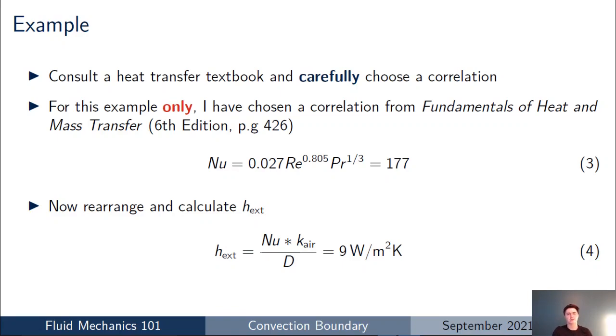So looking at that formula, equation 3, you can see that the Reynolds number is really representing the ambient conditions. So outside of your CFD domain, what's happening with the ambient conditions? In this case, you've got some wind. You've got wind at some velocity, and that's captured through the Reynolds number. And just as a reminder, the molecular Prandtl number is just a material property of the fluid. In this case, for air, it takes a value of about 0.7.